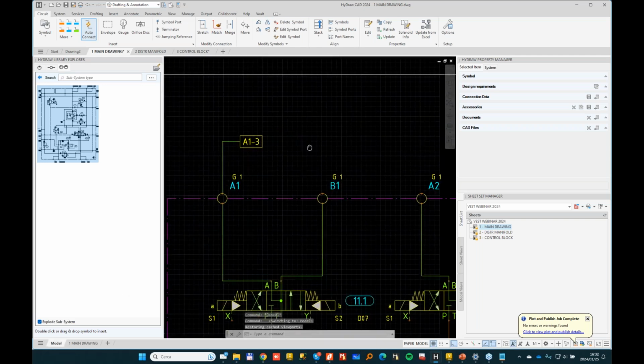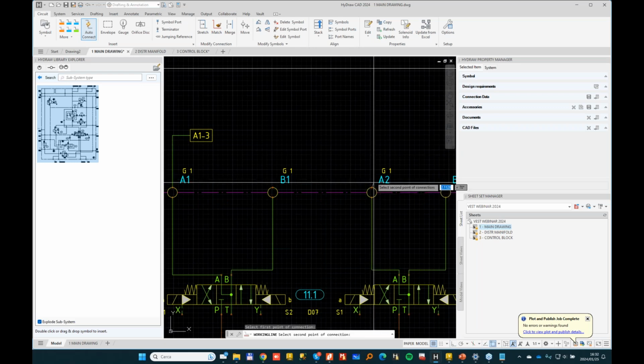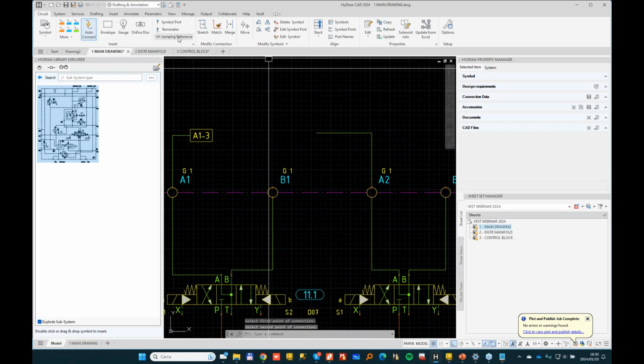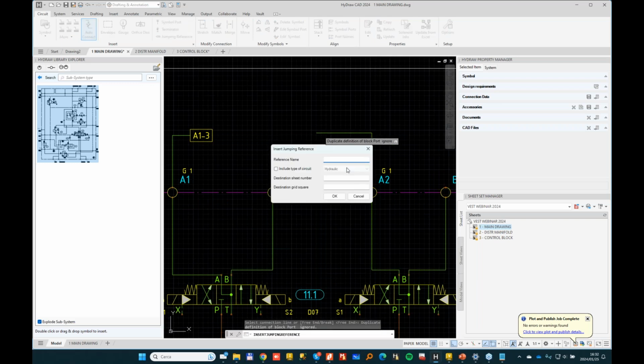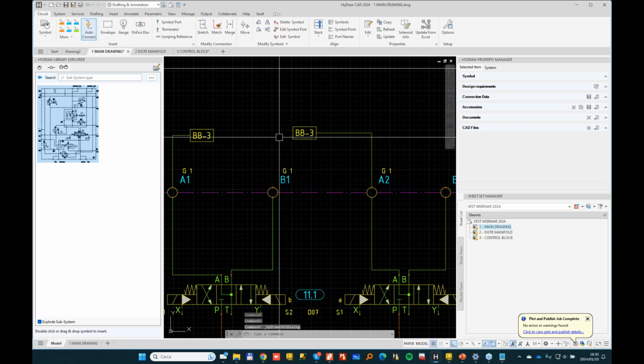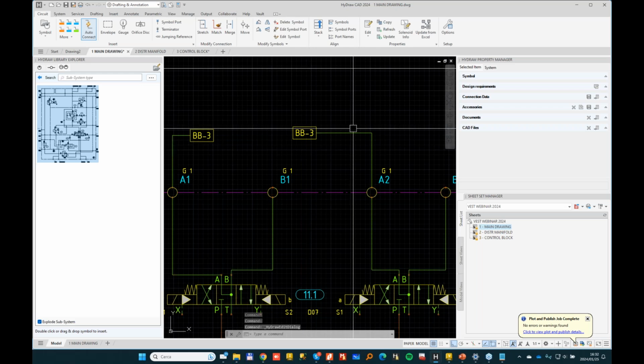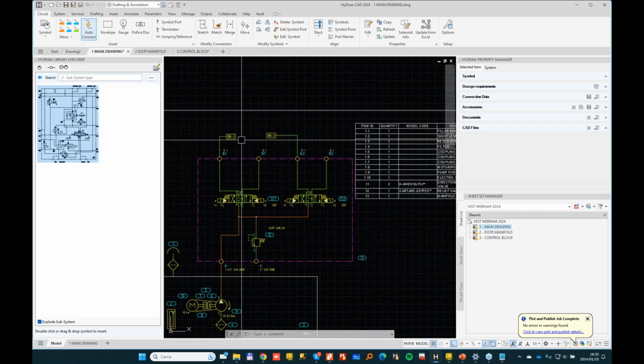If you do in the same drawing and you do the jumping reference, call it always A1. Now they are tied together, so if you change it, they will change in the same, but this technique works only at present in the same file. If we have more people adopting sheetset, then we may really consider also creating a cross-reference and more intelligence around this technique.